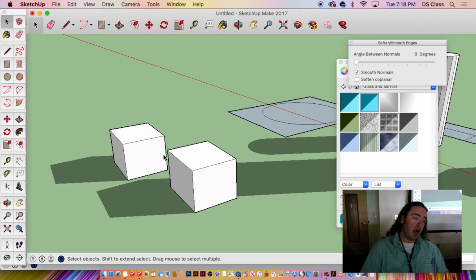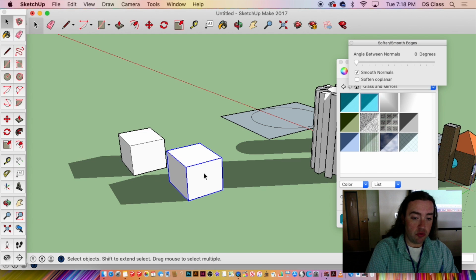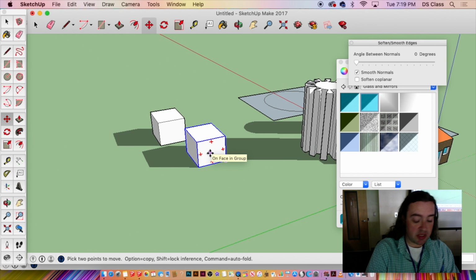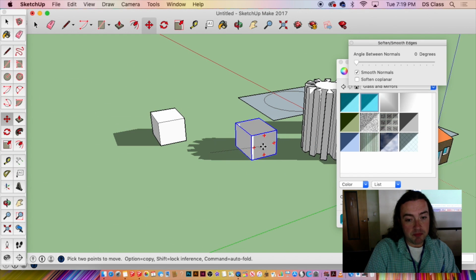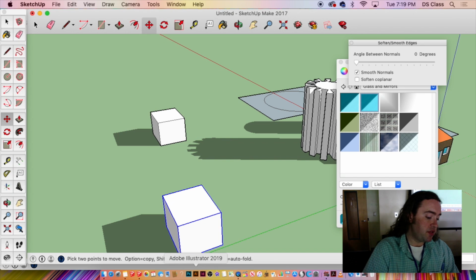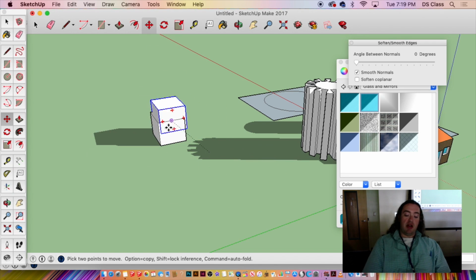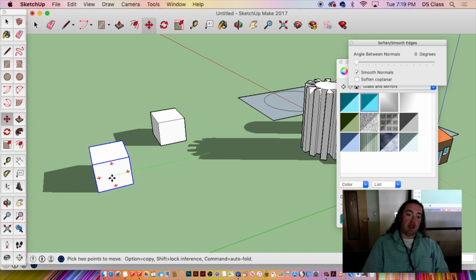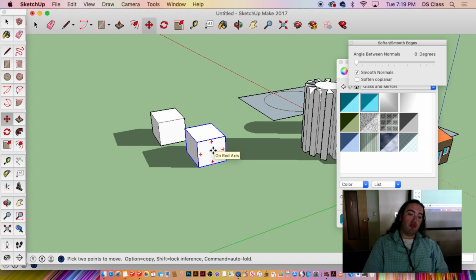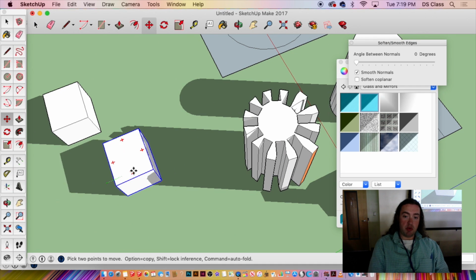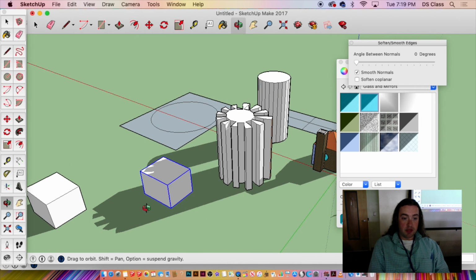A lot of times when I'm moving something, I will use the snaps to the axes, to the planes. Red, green, and blue. Check this out. Go to the Move tool. I click and let go. I've already started the moving process. Until I click that mouse button again, it's in movement. It's not going to stop. There's no inertia. Check this out. I can force it to go along with one of these. They'll snap automatically if you get it in the right spot, but I can force it to no matter what.